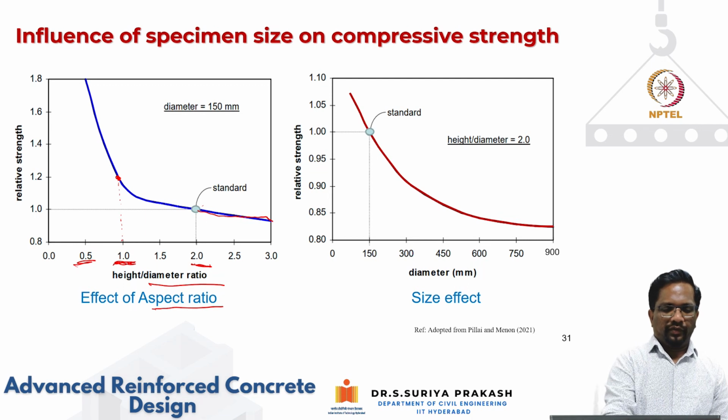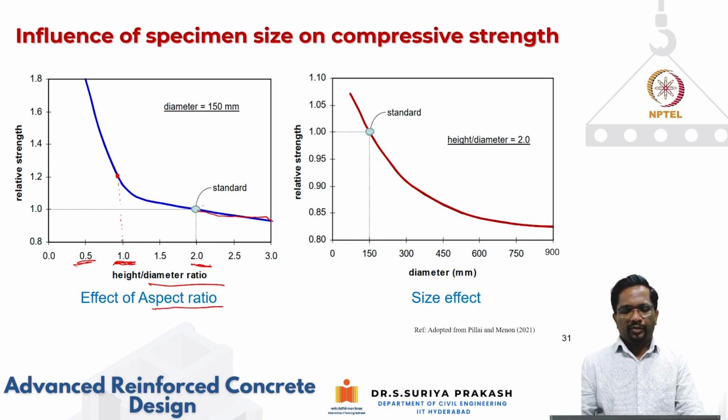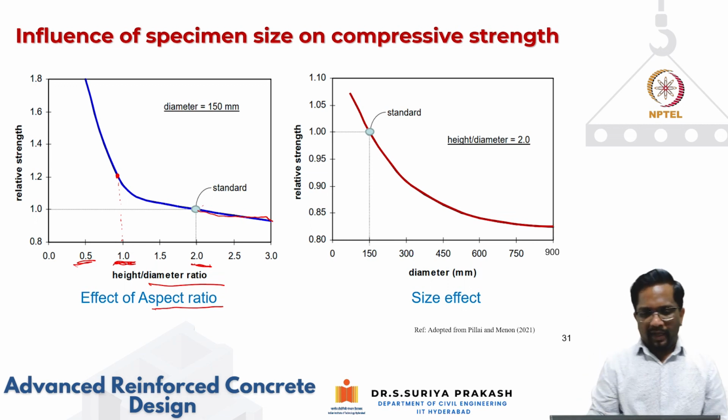So, if you use a cube, that's why the strength is amplified by about 25%. So that's how you end up with this factor. So this is why the relative strength shows a 25% increase that it is going to give you. But in actual material property, you have to reduce it by 0.8, because 1 by 1.25 is nothing but 0.8. Right? So again, size effect also.